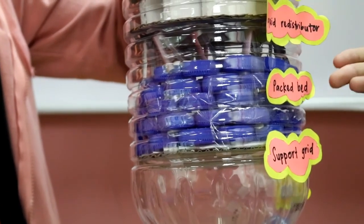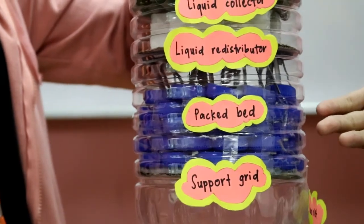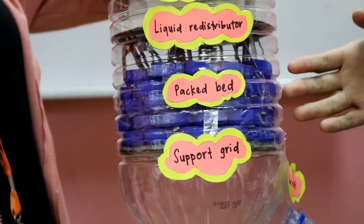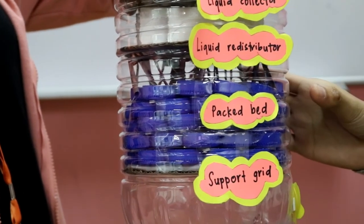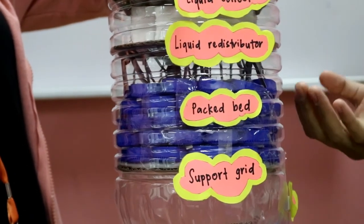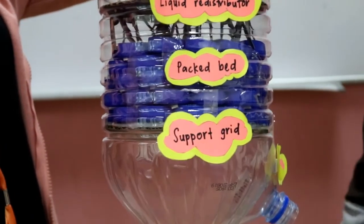The type of structured packing is thin corrugated metal plates or wire gauze. The function of the structured packing is that it gives a big surface area and enhances the spreading of the liquid, and then the liquid will go out at the liquid outlet. That's all. Thank you.